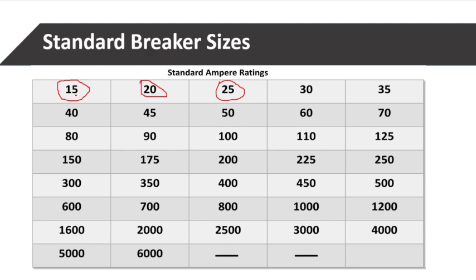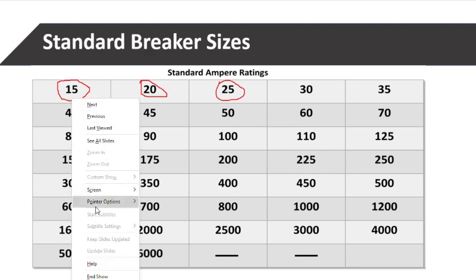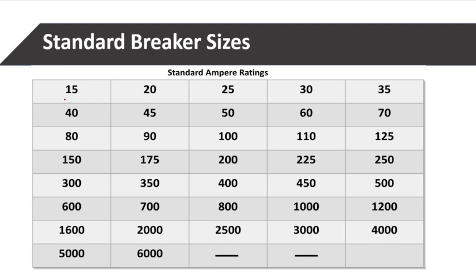Anytime you put on maybe this AC, the light will go off. You don't understand what is going on, whereas the problem is from you, the installer. You installed a 15 amps breaker while you're supposed to install a 25 amps breaker. You undersized it to 15 amps, maybe because you didn't see a 25 amps, or maybe your supplier told you that there's no 25 amps. Instead of going somewhere else to look for it, you went ahead and bought the 15 amps and installed it, and now the client just puts on his AC, and suddenly the breaker trips off because it cannot allow more than 25 amps to pass through it.